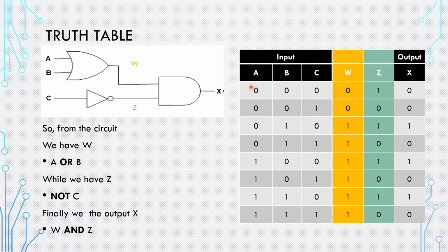This is what we want to study for any kind of circuit. As long as you know the typical operation for each individual gate, you're going to do it individually for each line, then find the final output for that circuit. So this is typically how to deal with a logic circuit. We have to convert it to a Boolean expression in order to study the output-input relation based on Boolean formulas. If you want to simplify it, then you simplify the formula. This is what we're going to take next time.